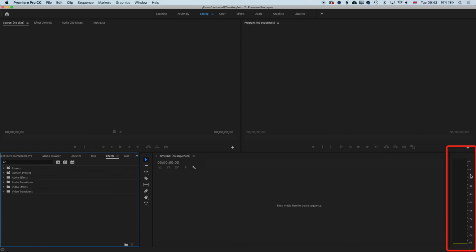If we have our sound too loud, then we can get something called clipping, which is basically the sound distorting. Anyone had a speaker that's blown, it clips at the top. We can make that happen here if we want to, but normally we're trying to manage our sound so that we're mixing audio and voice and any music tracks together so that they don't peak out and they sound good.